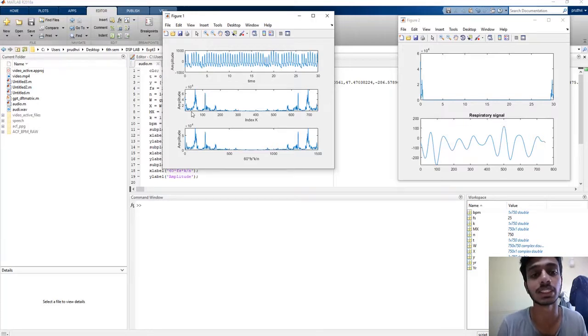Since MATLAB uses my processor, and since my processor can handle the computations required for 750 samples, I have just used a simple DFT which I have written and not FFT. And this is the Fourier transform with respect to the frequency.